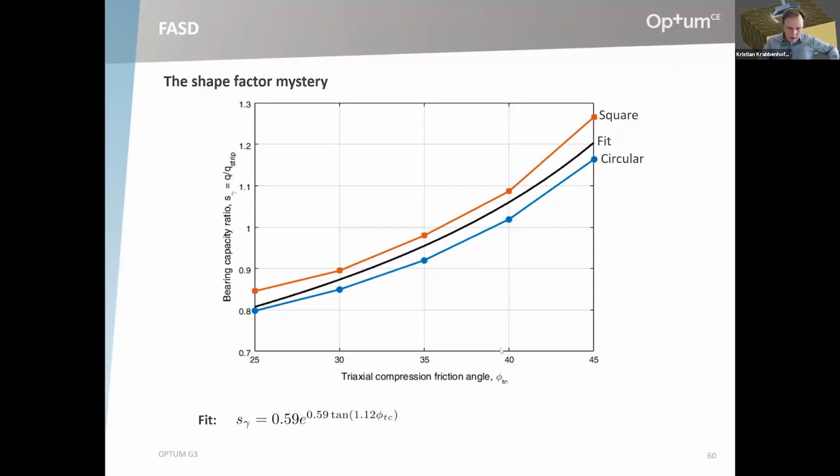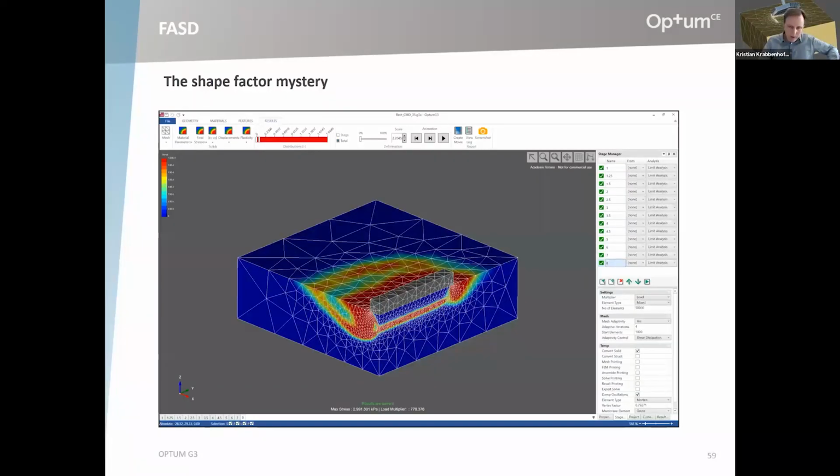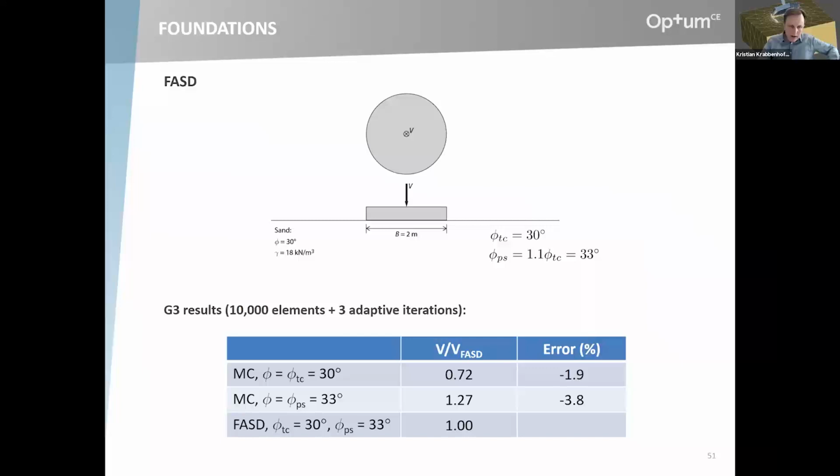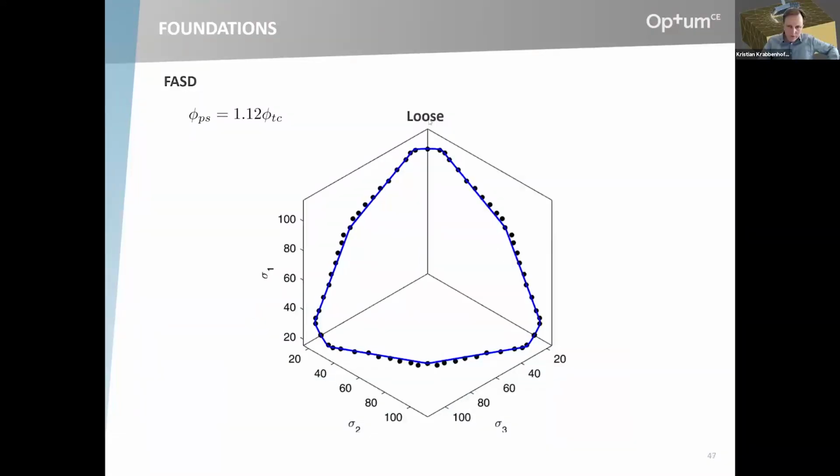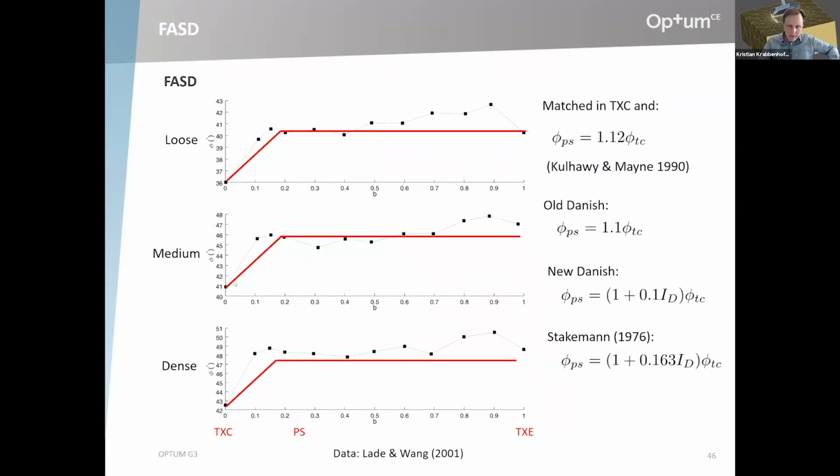Okay, then there's a comment that someone has carried out a lot of tests and gets the same friction angles. Again, you're welcome to contact us for further discussion, but this type of trend, with the triaxial compression angle being smaller and then the friction angle gradually, or even abruptly, increasing, is a very consistent trend that you see in lots of other experiments.